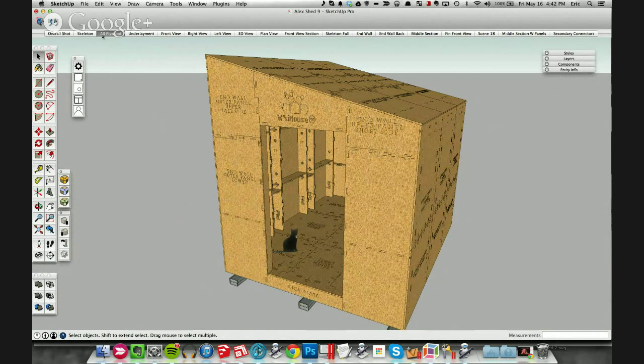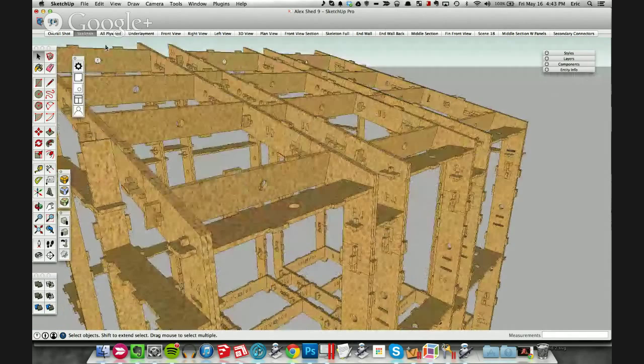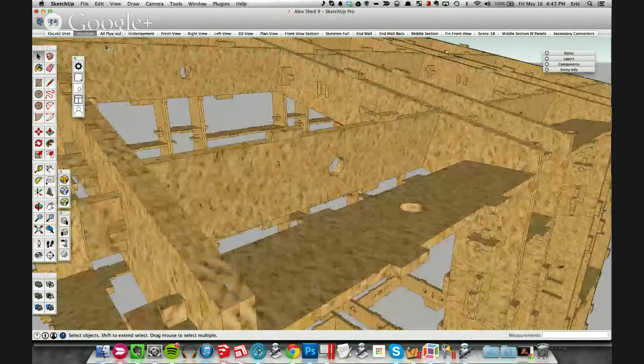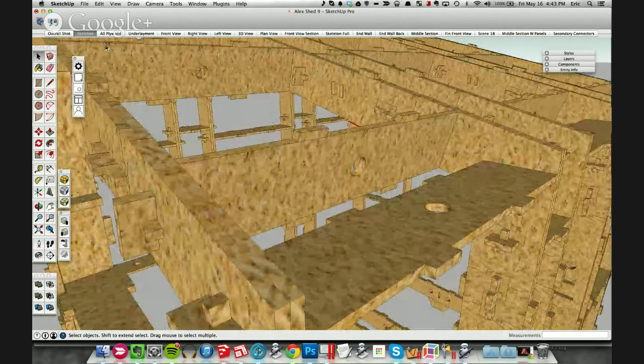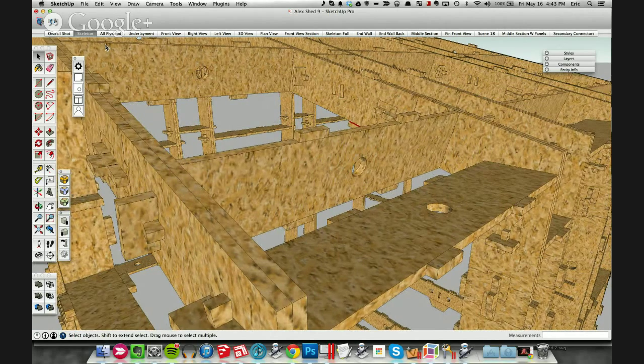And the idea is the entire house is made out of plywood, and it fits together with almost no metal fasteners at all. It's all peg and wedge construction, so we can take a look at one of them here. This is a design that I've been working on. And so everything fits together. These beams come together and they get wedged in. This is a lot like a post and beam house. So if you've ever seen an old post and beam where one beam slots into another and they hammer in a big wooden peg into it, that's what this is, except the big difference here is instead of doing it with old tree logs that are cut down into squares, this is done with off-the-shelf plywood.